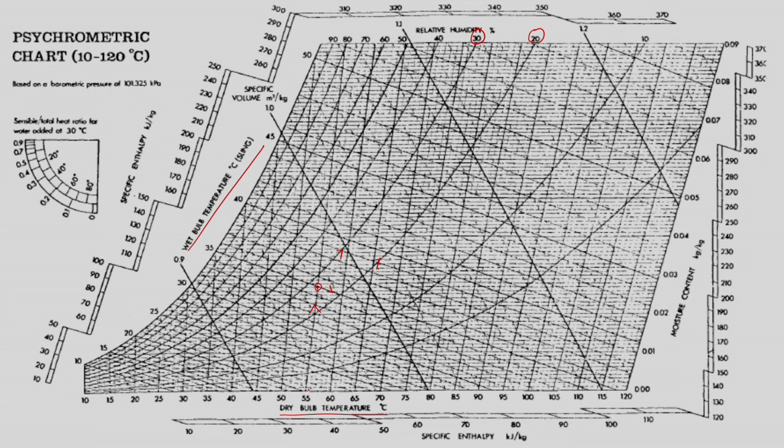So, what we have seen is dry bulb 55 and wet bulb 35, right. I put this as 0.1 here. This is the 20% relative humidity line, this is the 30% relative humidity line. So, if you go from here it is around maybe I can say 28%. So, from dry bulb and wet bulb I can get to know the relative humidity.